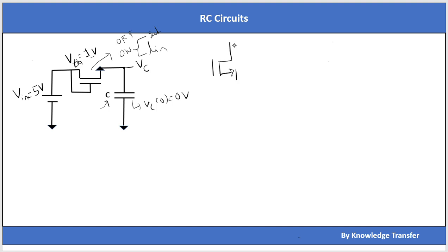Okay, so there is a MOS here. This is drain, this is source, and this is gate. Here we can say that gate and drain are shorted. Because drain is 5 volt and initially the cap is uncharged, I can consider source equal to 0 volt. VG is always 5 volt, in the same way VGS equals 5 volt, but VTH of the NMOS is given as 1 volt, so VGS is greater than VTH. I can say that the NMOS is in on state.